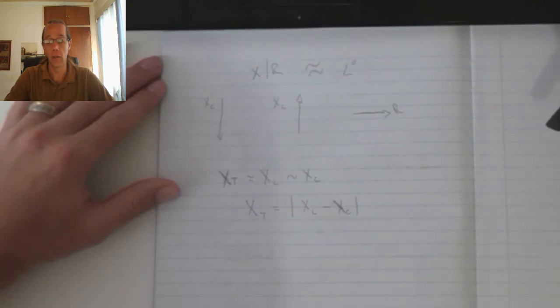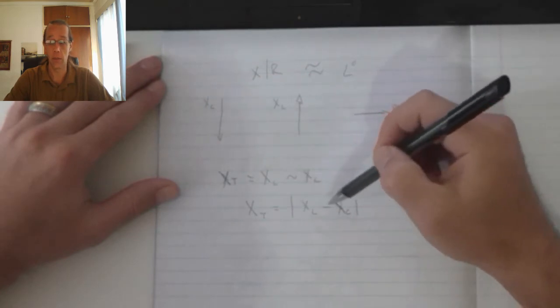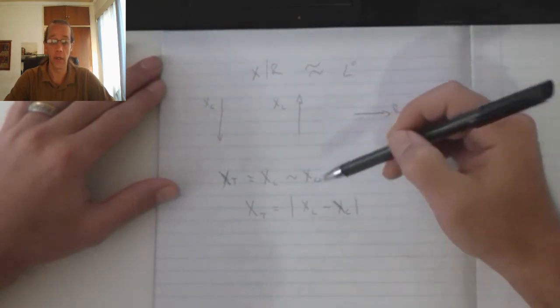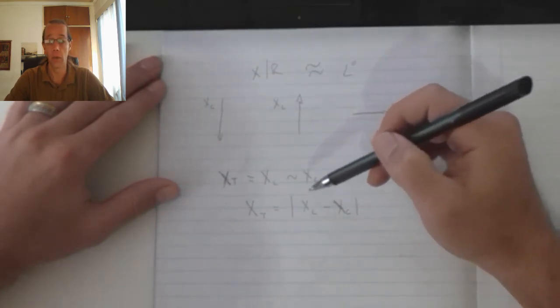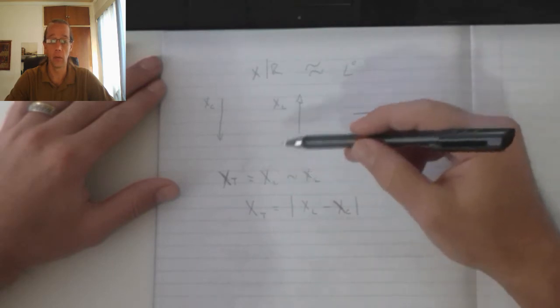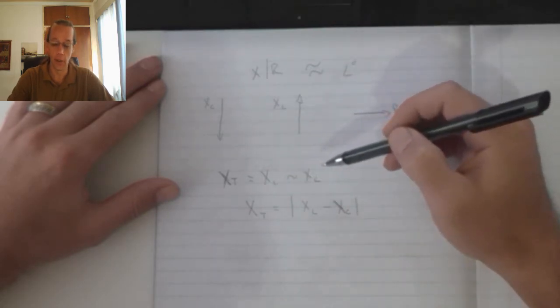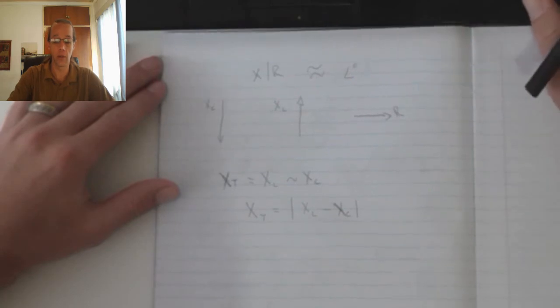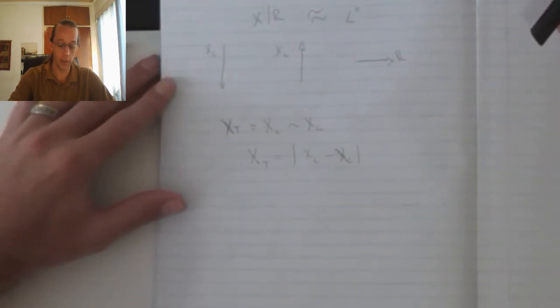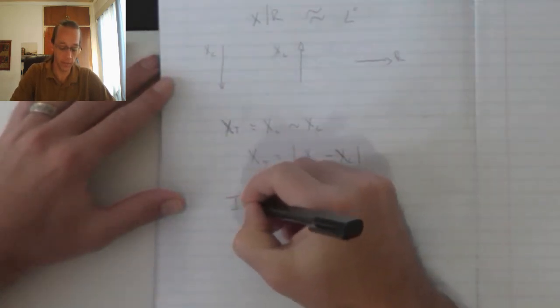Now, reactance we determined is the apparent resistance of the inductor or the capacitor due to the frequency that it experiences. Because when it experiences a frequency, there's a phase shift, we need to incorporate that when we calculate the overall opposition to current. That overall opposition to current is called my impedance.